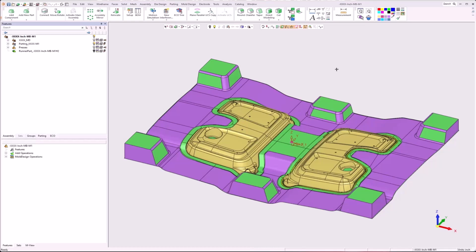The cut bodies will update when you update the lifter bodies, and we're going to eliminate manual features like fillet and trim face, which if you go that route, when you make a change, you get a lot of suppressions, and it's due to the manual picks in them. So again, a lot better technique using the solids, as you'll see.